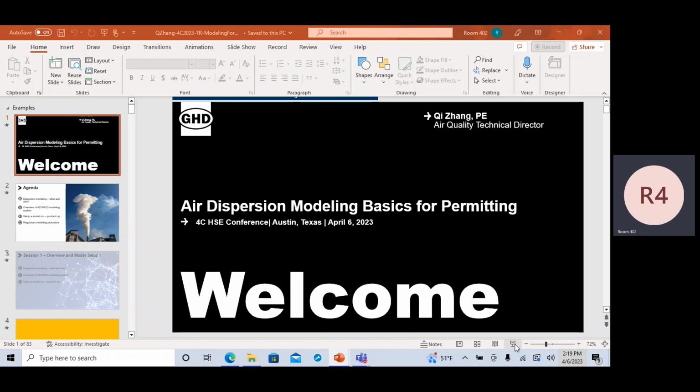Your base information can be downloaded from the MRLC, the Multi-Resolution Land Characteristics Consortium. This is the website, and that picture was pretty old. NLCD 2016 is now available, and now you have 2019 data. You download these 3 types of surface characteristics for your model run: a land cover, a tree canopy, and impervious cover.